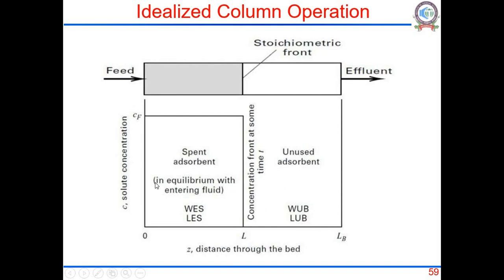In this part, no adsorption is happening, no ion exchange is happening, because it is already at equilibrium. So we call this the length of the equilibrium section, or weight of the equilibrium section of the resin. This part we call the length of unutilized bed, or weight of the resin unutilized in the bed.